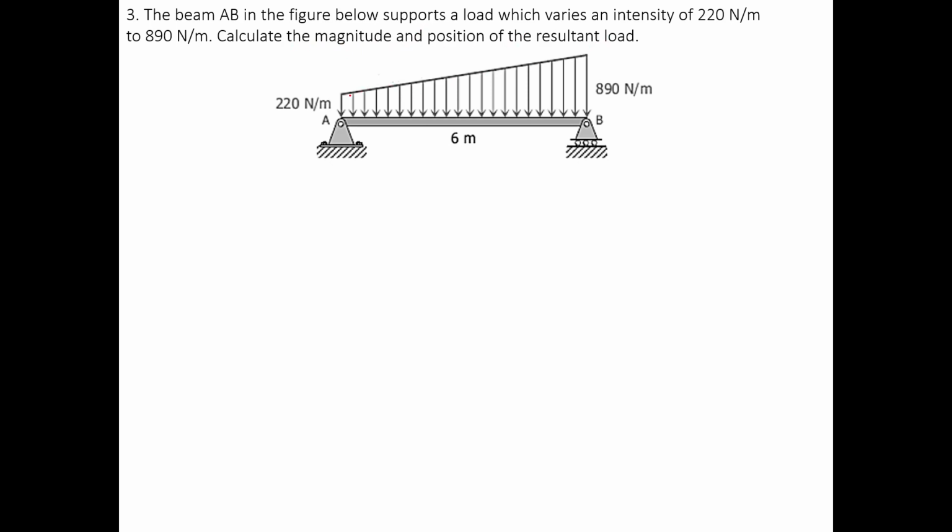Earlier, as we have seen in the previous slide, we can divide this into a rectangular load and a triangular load. This one is 220 Newton, and the upper portion from 890 on the left side minus 220 becomes 670 here, the triangular load.